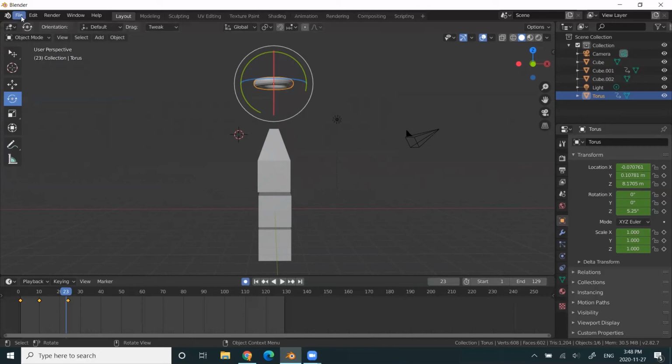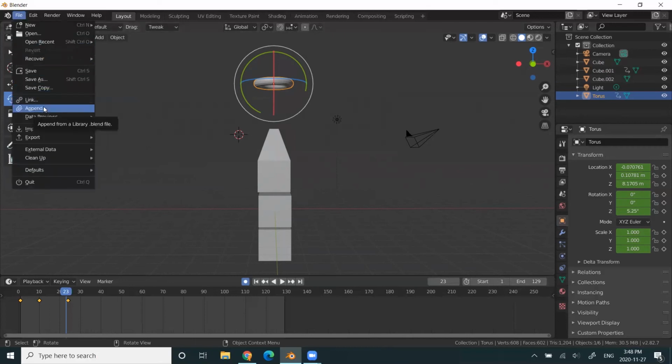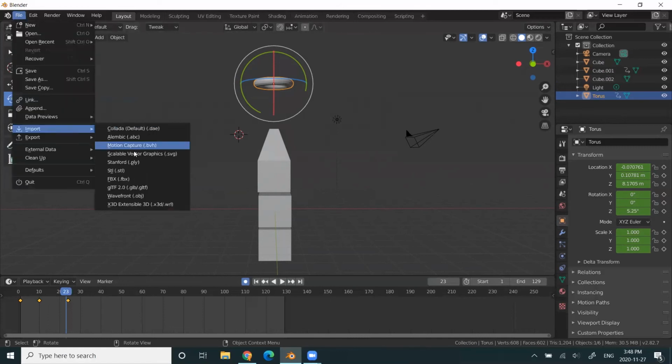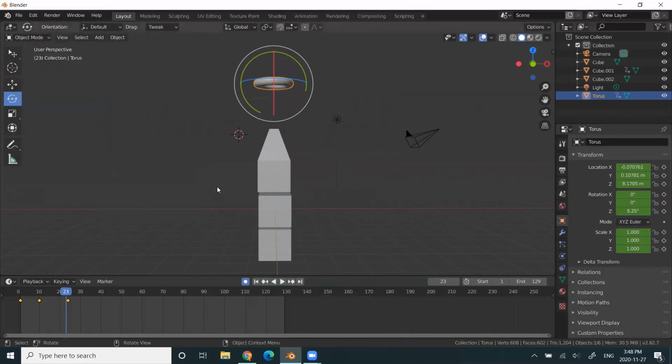Yes. So you want to make sure that you import all the different parts into one Blender file. You can do that with File, Import, look for the OBJ, and import it all together. Then we need to align it, or put it together however it's supposed to be put together. Make sure the texture is reading properly. You can check if the texture is reading properly if you press viewport.